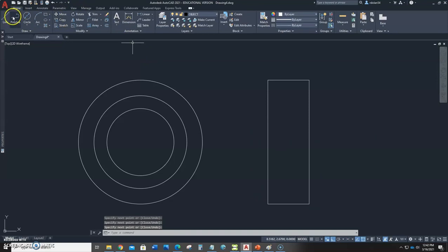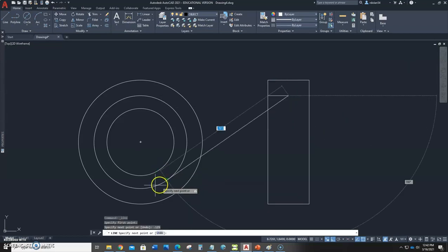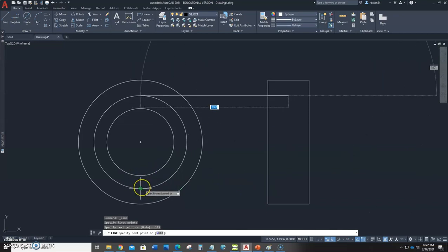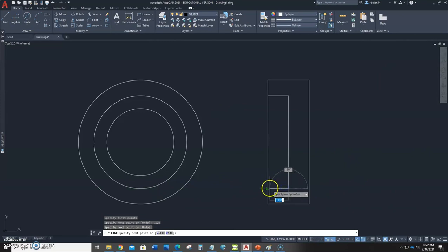Okay, now I'm going to draw a line, and I'm going to draw all these as solids right now. So I'm going to go quadrant from here, and I go down 0.25 or over 0.25. Nope, 1.5. 0.125. Right there. 0.125 right there. Go down to this one. Make sure that says quadrant, and I can just slide it right over to there. And draw one more and go from here, quadrant, there to there. One more again, quadrant. Make sure that when you do that it says quadrant, and you get the green line. Go here, you'll see intersection here, and then you'll see perpendicular there. Okay, so now I have that.